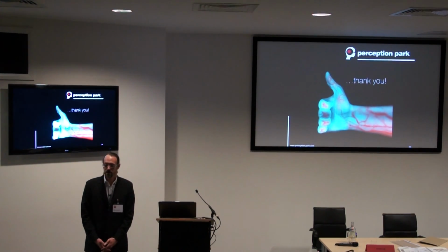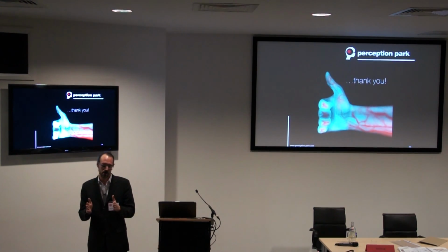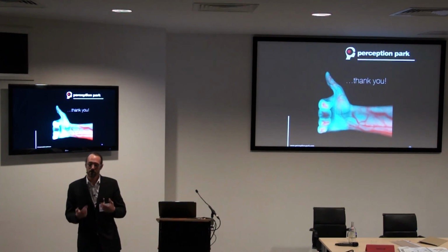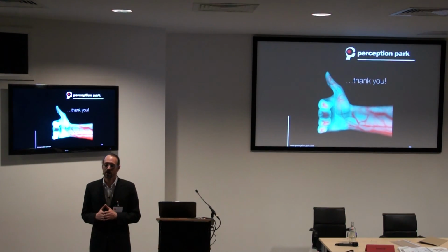We have to differentiate. There is a digital sampling, where you get the information, and there is the true optical resolution. The sampling is often done in a range from 2 to 4 nanometers in the NIR range. The real optical resolution, depending on the spectrograph, is from, I would say, 4 to 8 nanometers.